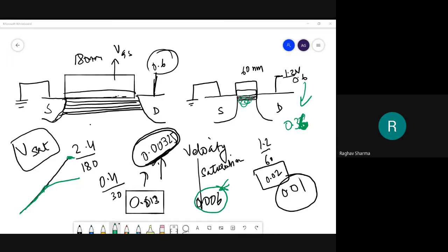So what was the 150 millivolt that you mentioned just? Oh, so VT से, so saturation condition जो कही जाती है, that is typically understood to be 150 millivolt, 6 kT by Q above threshold voltage. 1 kT by Q is around 26 millivolts at room temperature. K पता है ना आपको? K, what is K? Boltzmann constant.